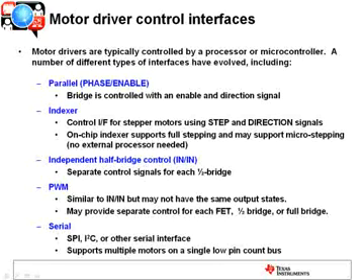It's also common to see PWMs control individual FETs, so a high side or low side, control a half bridge, or even control a full bridge. So there's some variety in those PWM interfaces. And finally, you've got a serial interface, and those are great for controlling multiple motors on a single low-pin bus. So for example, there's some drivers in our portfolio that you can hook up to 9 drivers on an I2C control bus.